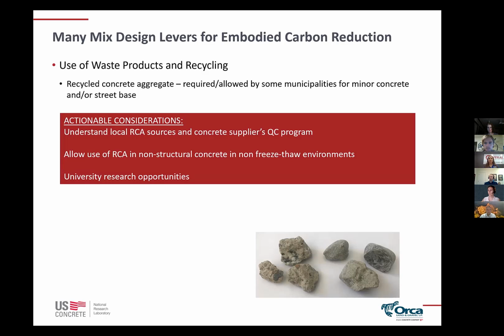And so actionable considerations here are to understand the local recycled concrete aggregate sources and the concrete supplier's QC program, because that can help you gauge then what type of applications you want to be able to use it in. Allowing the use of recycled concrete aggregate in non-structural concrete applications is something that's a pretty easy thing to implement.